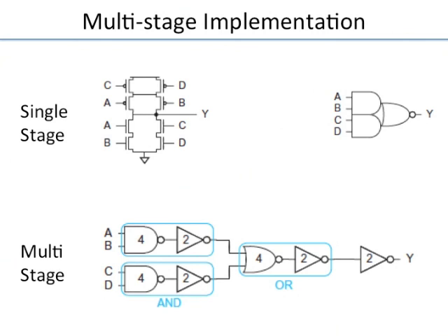So one of the questions is, which of the two approaches is better? Clearly between these two you see, as many of you pointed out, that this seems to be very compact, right? There are basically 4 plus 4, 8 transistors, whereas here a NAND2 itself has 4 transistors. An inverter has 2, that is 6, 6 plus 6, 12, plus another 4, 16. So let's ignore these two inverters. Suppose we were to optimize: you have 16 transistors, this is 8. This has twice the number of transistors.